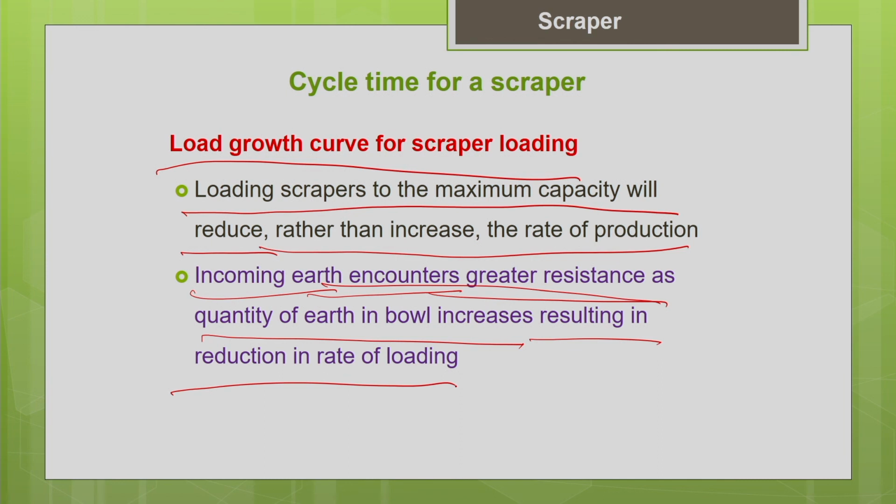of loading. So, the material which is lying inside the bowl, when the amount of material inside the bowl starts increasing, will start offering resistance to the material which is trying to enter the bowl. So, that is why the loading rate starts reducing. We can easily understand that concept by drawing this load growth curve.